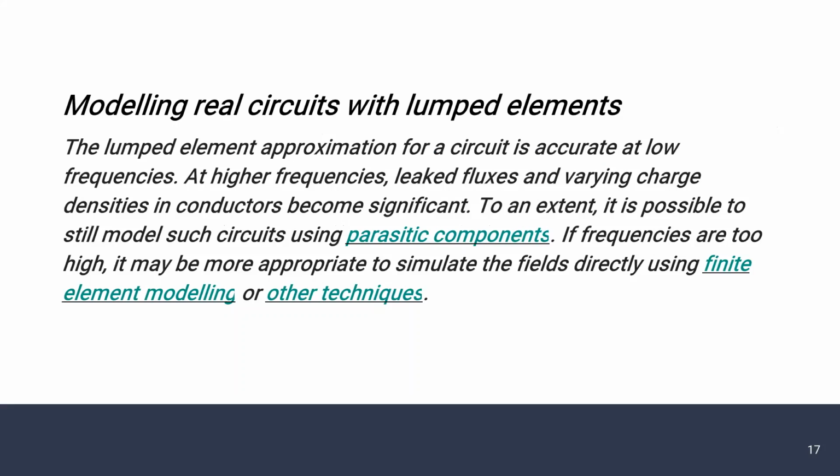Modeling real circuits with lumped elements. The lumped element approximation of a circuit is accurate at low frequency. At high frequency, leaked flux and varying charges in the conductor become significant to an extent. It is possible to still model such circuits using parasitic components. If frequencies are too high, it may be more appropriate to simulate the field directly using finite element modeling or other techniques.